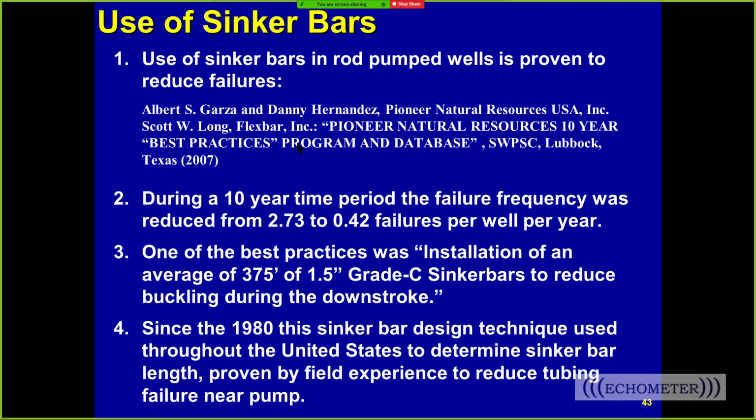And we were having frequent holes in tubing down near the pump. And we started using this design method for sinker bars at Emerald Hess. And all the holes down in the pump due to rod-on-tubing wear went away. As soon as we started using sinker bars, it was like magic. And so I became a big advocate for sinker bars, and Elton Smith worked for Emerald Hess.